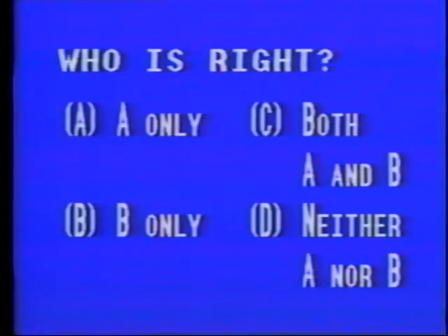Two technicians are discussing an engine that tends to overheat only when sitting in traffic. Technician A says a faulty coolant fan clutch could be the cause. Technician B says the thermostat could be stuck closed. Who's right? A, A only, B, B only, C, both A and B, D, neither A nor B. Our main clue here is that the engine only overheats when sitting in traffic.